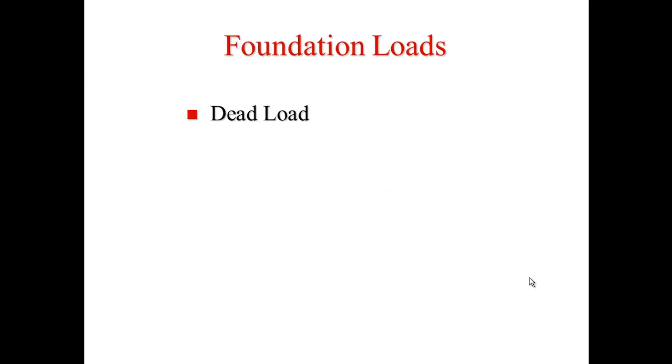Foundation loads. Again, dead load, the weight of the building itself, is going to stay permanent all the time. Live loads, those moving parts and things that can be changed or moved around. Wind loading. If we've got 50-mile-an-hour gusts of wind outside, we want to make sure that we're maintaining the stability of the building during those types of wind loads from any direction, whether it's north, south, it doesn't matter. We need to make sure that our building can handle any type of wind load.